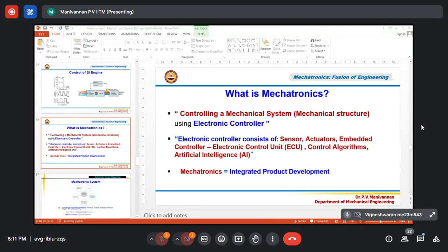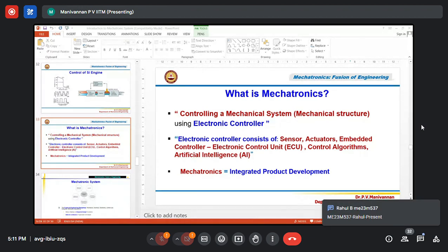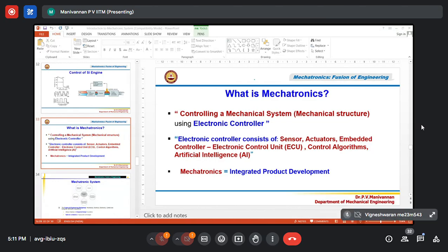Inside it you have a coil, you supply voltage, it produces a magnetic field. The magnetic force opens or closes the fuel plunger or needle valve of the injector. So fuel is controlled. Quantity of fuel is controlled. So that means you need electrical knowledge to design the solenoid. Then you need mechanical knowledge to design the injector itself. It has many mechanical parts. Okay, so to develop this, you need an engineer who knows electromechanics, correct?